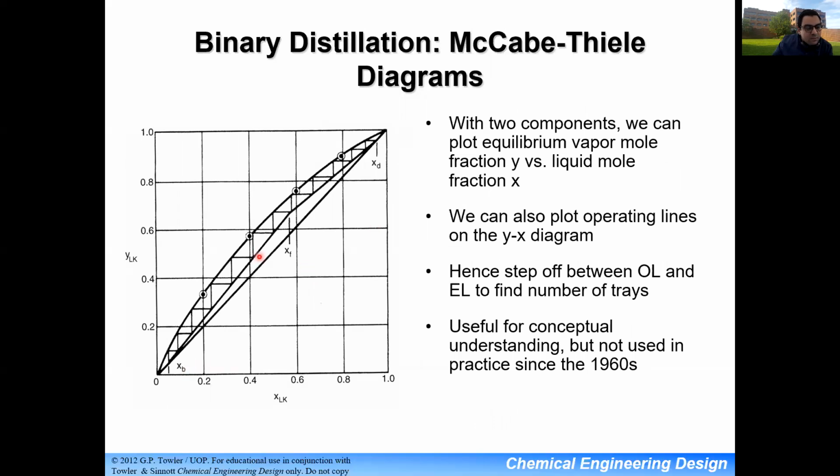But this sort of diagram, once you cover it in mass transfer, is the starting point to design your distillation column. Usually I have two components. I draw two lines here. I have my equilibrium line, and then I start staging off. And if I count these number of stages, this gives me an indication of the number of theoretical trays that this distillation column will have. And then I take this number of theoretical trays divided by the tray efficiency, and I get the finalized number of actual trays in my distillation column.